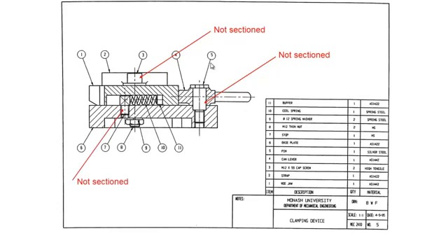We also have this part number 7, which is our stop. It also hasn't been sectioned. And you might just note on here we have this cross here, and if you looked that up in your drawing handbook, that represents that it is a flat surface, which compared to this other non-section part here, which is a buffer, is actually a round surface.